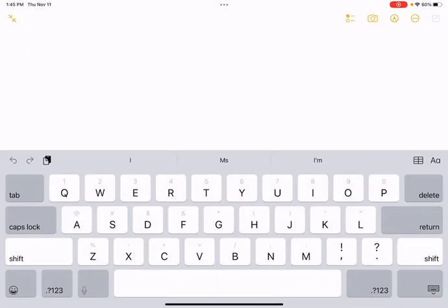All right, so this video is going to be the first video where we do a cycle. A cycle is a series of processes that happen one after the other, where by the end of it, you end up where you started in terms of the state of the fluid. The cycle we're going to do today is called the Otto cycle, O-T-T-O, which is a little confusing because it's actually the cycle that's used in a car engine.